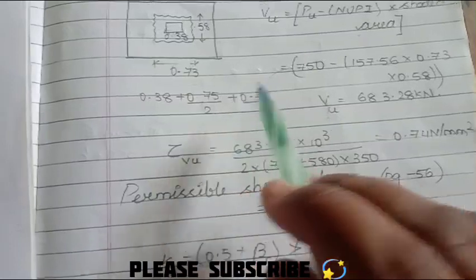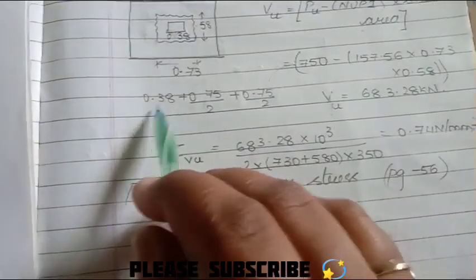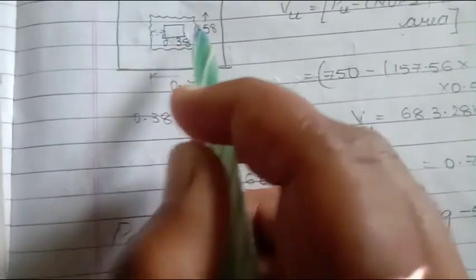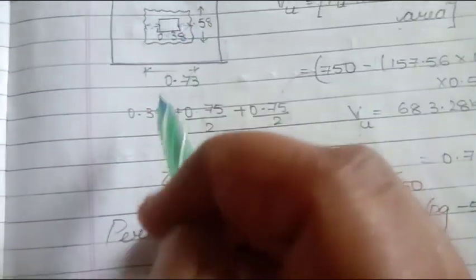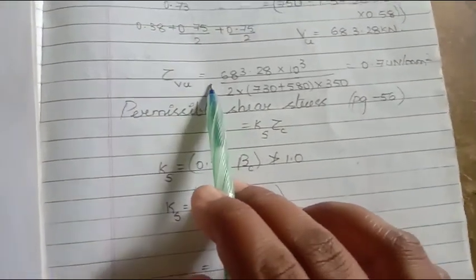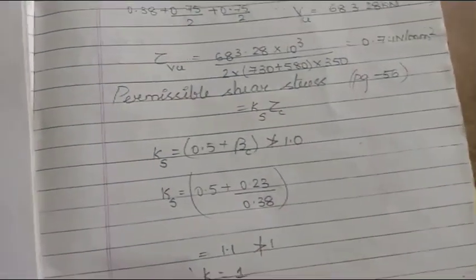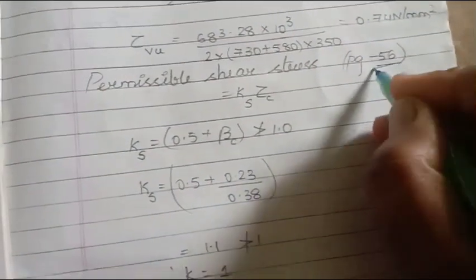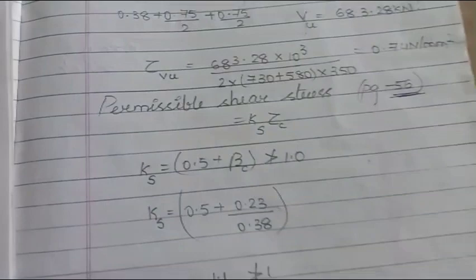At a distance d by 2, to get this value, 0.38 plus d by 2 plus d by 2, because both sides. Here we are having d by 2, here we are having d by 2. Next, you will be getting tau v. Again, here we have another formula to calculate the permissible shear stress. It is on page number 56. I will show you.